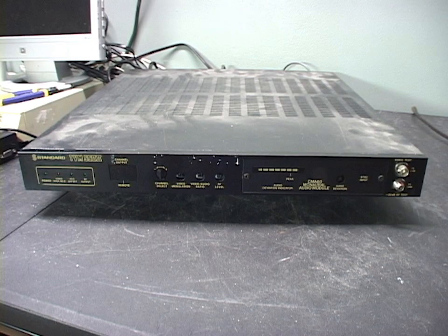And the cable head end is also listening onto the main cable network, listening in onto these special channels. It picks up your feed, remodulates it onto a normal channel, and sends it out for the end subscriber.